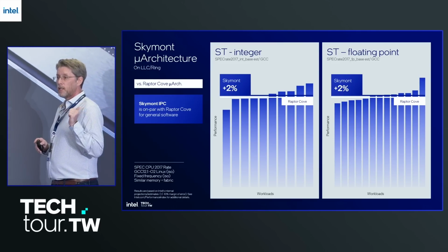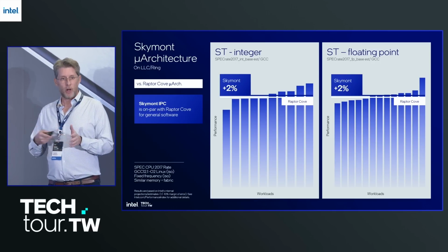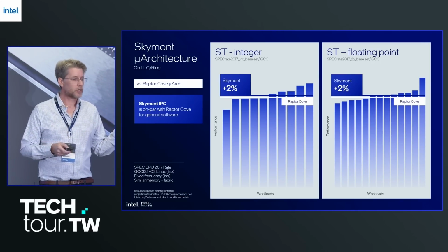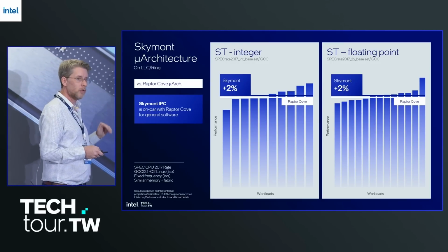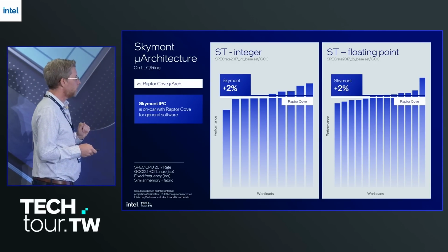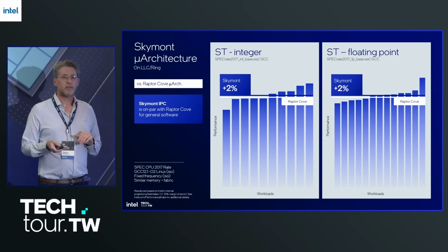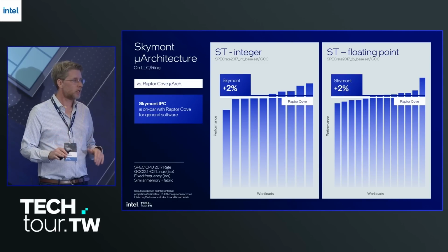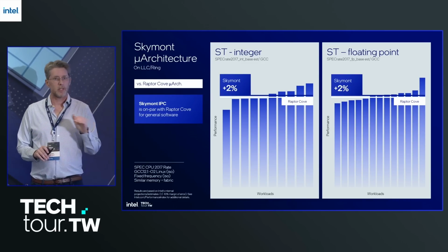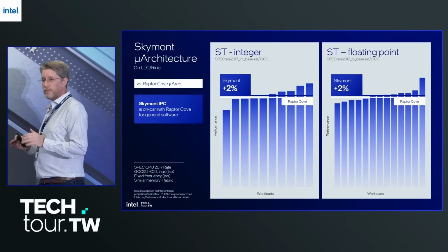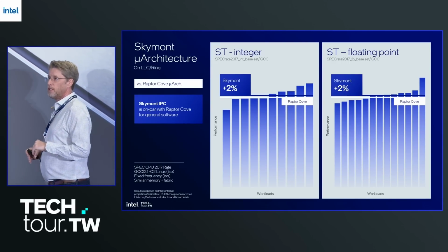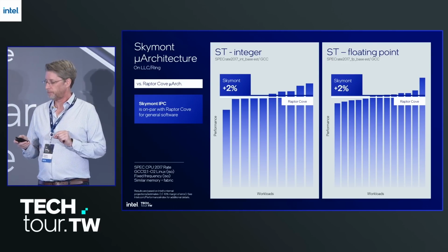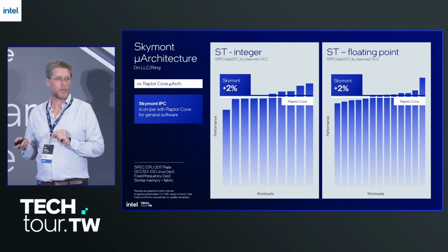Now before I said, when comparing against E-core, that it was all positive, there were no negatives. Here, it's a trade-off. Here's an S-curve. You can see there are a few below the line. You can see there are a few above the line. So I don't mean to tell you that all workloads are 2% faster in IPC on this IP. It's a little bit of trade-off. But fundamentally, geomean, spec int, and spec FP, 2%. So let's map that to power and performance.